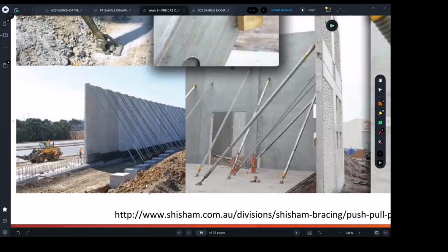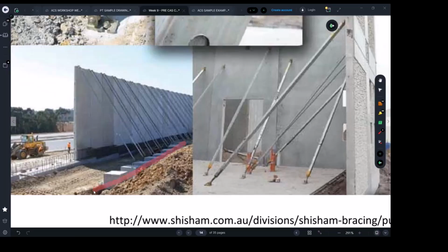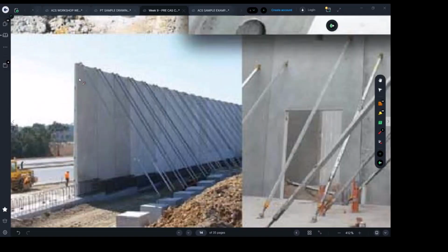Sometimes the builders may build a strip footing temporarily here to get those propped, in case maybe this was a road or asphalt, or maybe it's part of a garden. You don't know what you have here. Maybe it's landscape and you don't have any structure. You will have a roof here in the future. Yes, that's fine, but maybe here you don't have any concrete in the future. So in this case, you have to go with those temporary blocks to help you stabilize what you have to stabilize.